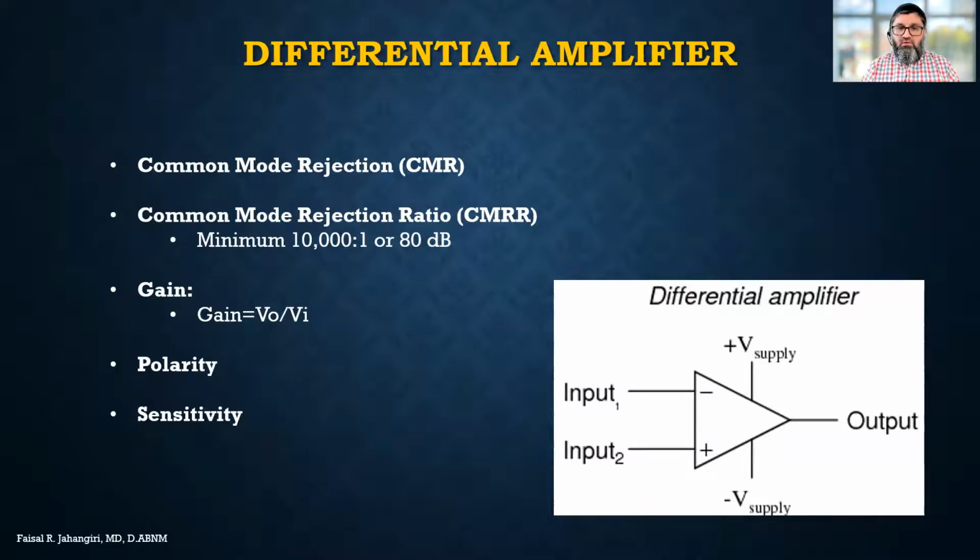If it is 2 microvolt signal coming into the active input and minus 2 microvolt coming into the reference input, the plus 2 in the active becomes minus 2. So minus 2 plus minus 2 will be minus 4 microvolt on the screen. So the signal will show on the screen as downward 4 microvolt.